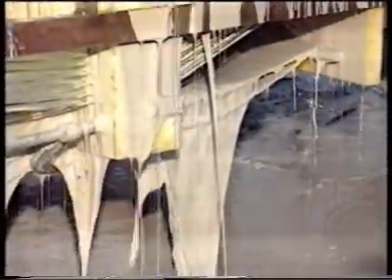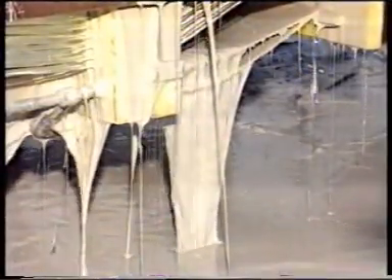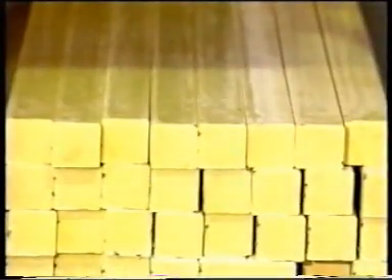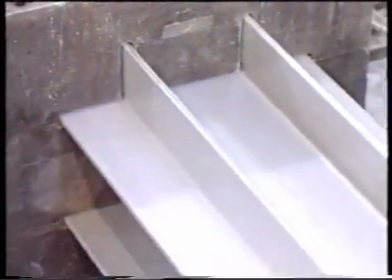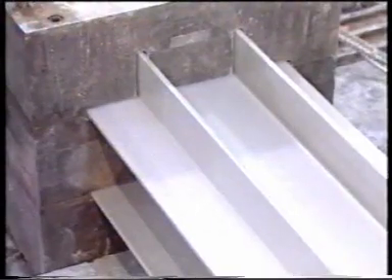Material waste for pultrusion is low because excess resin is squeezed off the fibers and returned to the wet-out station. Pultrusions can be hollow or solid. Pultrusion dies may be fixed, or one may float, such as internal mandrels used in making hollow parts. The pressure applied can be hydraulic or mechanical. Although part cross-section is typically constant, floating mandrels can permit some variation.